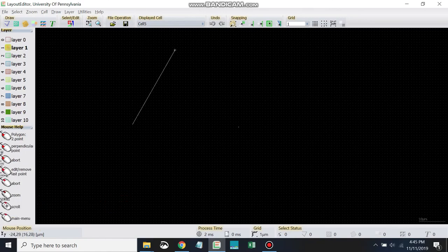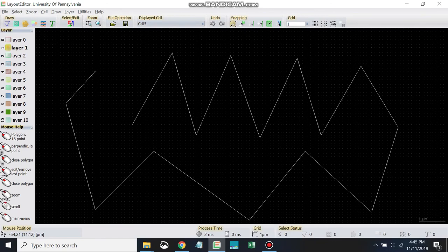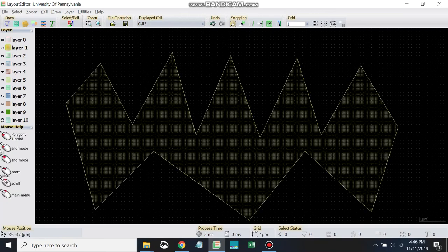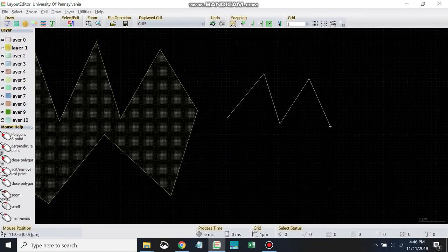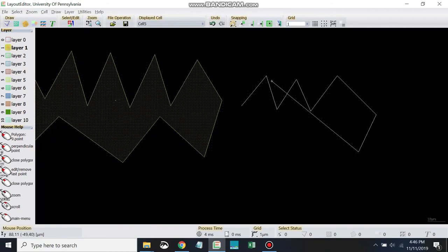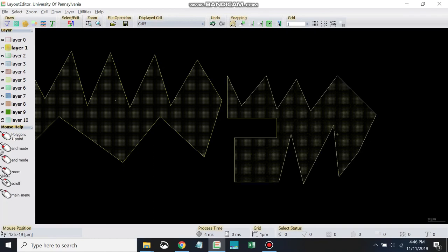And then it works the same exact way as the path command does. Except the difference is, I'm going to go ahead and get a little aggressive here. The difference is when you finish the shape, instead of just finishing at the last point, it'll snap closed to where you started and then fill that in as a polygon. So then it's something like that. And also the shift trick that we just learned for the path command also applies here too. So that's another really handy one. So I can hold shift, just like the path command, and bang, there we go.